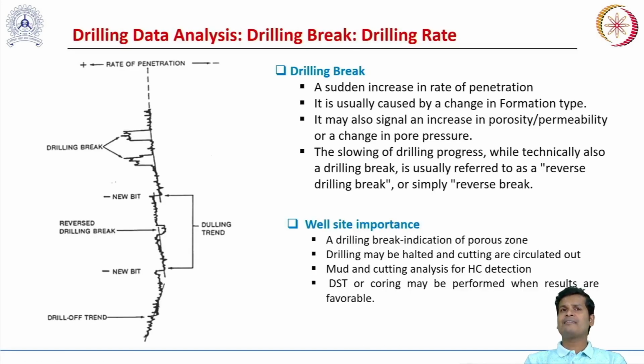So let us analyze the drilling parameter. Drilling parameter analysis can also give us a lot of information about the type of formation being drilled and the fluid it may contain. Generally, most of the information could be interpreted in terms of rate of penetration. So during drilling operation, we continuously analyze the rate of penetration or the rate of drilling, at what rate we are currently drilling at the well depth. So rate of penetration can be analyzed in terms of drilling break or reverse drilling break. A drilling break is nothing but a sudden increase in the rate of penetration or rate of drilling.